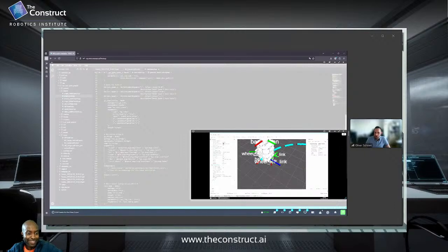Yes, true. So for the joints that are not fixed, but for example rotate continuously, like the wheels, I need these joint states to actually display it in RViz as well. Yes, that's correct. You actually corrected the way I asked my question, so thank you very much. That's exactly how it works. You don't need it for the real robot, but you need it for simulation. So yeah, that's cool.